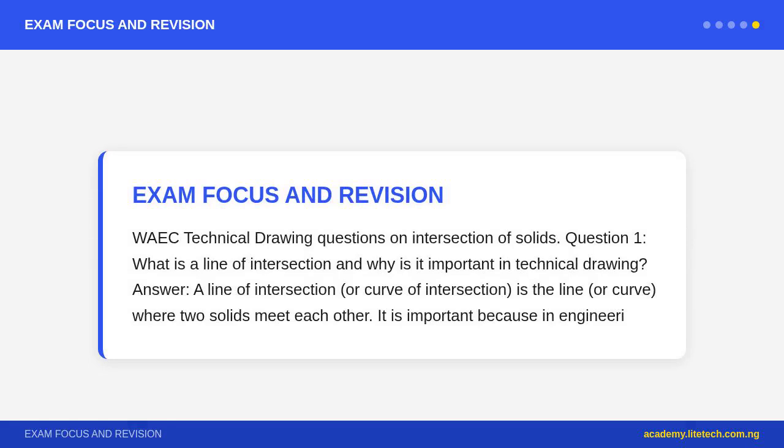Question 3. When finding the intersection of a cylinder with another solid using the generator method, why are more generators better? Answer. The generator method finds individual points on the intersection curve by locating where each generator, a longitudinal line on the cylinder, intersects the other solid. With only a few generators, only a few points are found, and the curve can only be drawn approximately between them. More generators give more points, which allows the smooth intersection curve to be drawn with greater accuracy. Fewer points can result in a straight line approximation that misses the actual curvature.